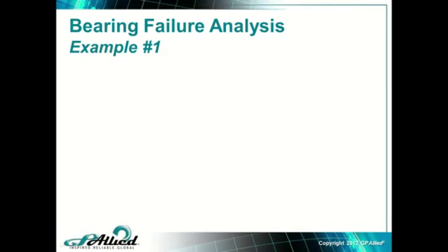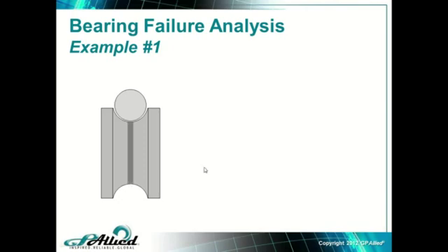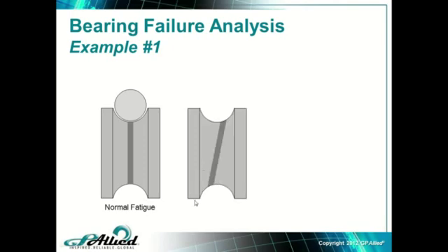I was working with a gold mine, and this guy had some bearings that they had removed as a result of their vibration program, and he was kind of showing me some of his war trophies, we call them. Now, here's an inner race. We know that the ball sits there, and we expect the subsurface fatigue, when it begins, to go right down the center of the race, something like that. So this would be normal. Well, he brings me one that looks like this.